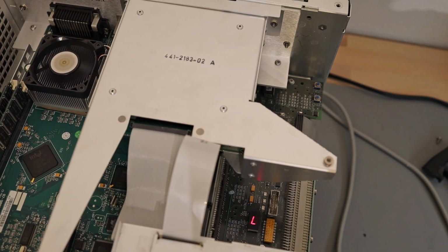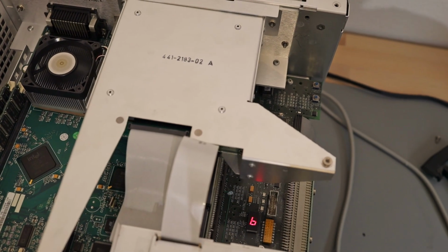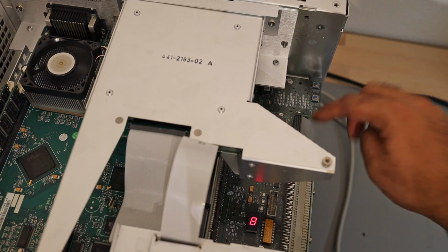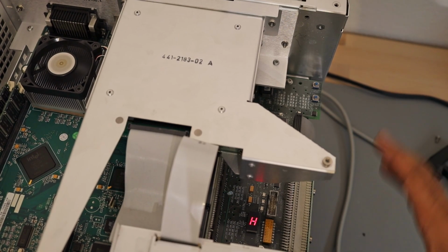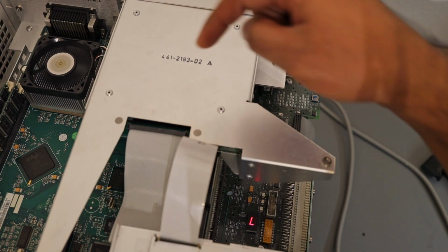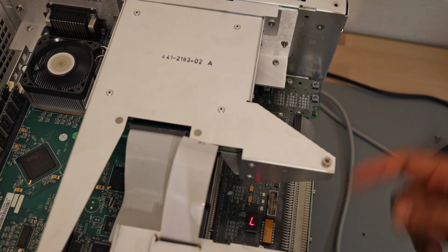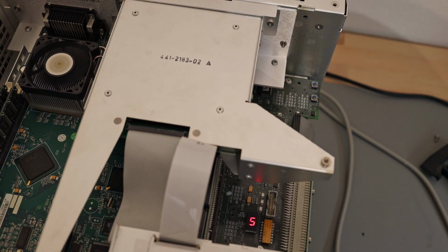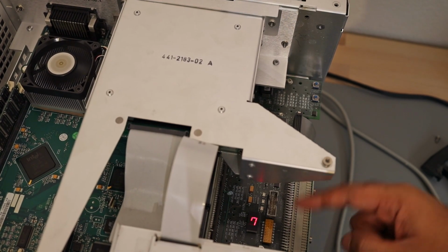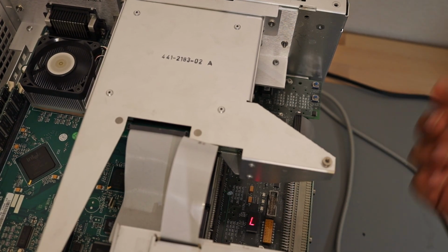And you will see the board primary application. The primary problem with this instrument, why it's not starting, is that the application starts, and waits for this acquisition board to start, this VxWorks board, but it cannot find the appropriate setting which is supposed to come from memory on this board. So that's why it keeps going round and round in the loop. So that's why you see it's not reaching a status. It goes into this 8 and now H, 7.